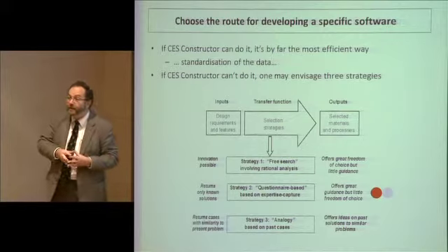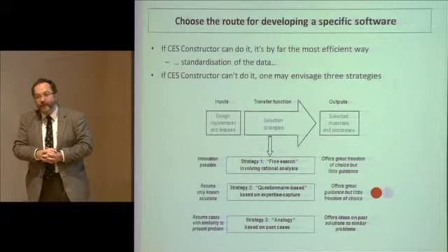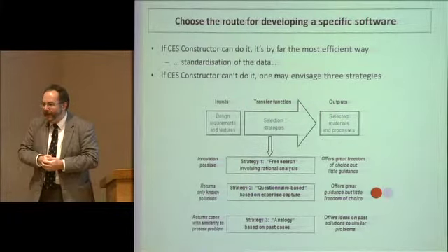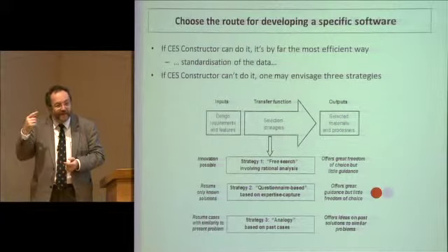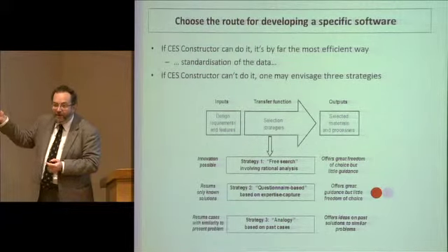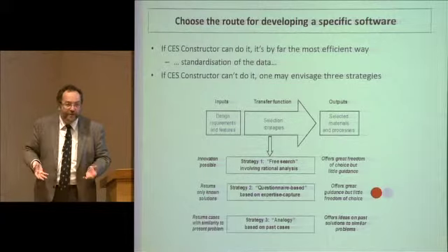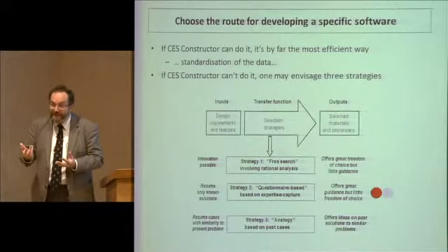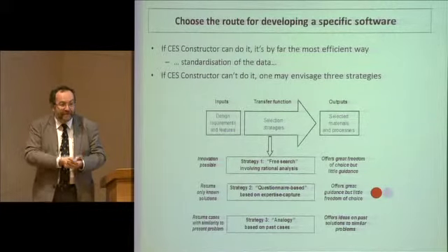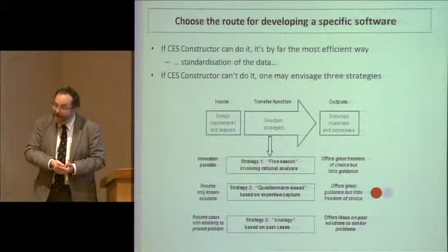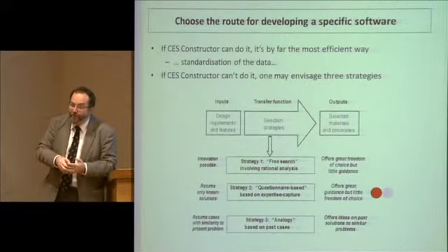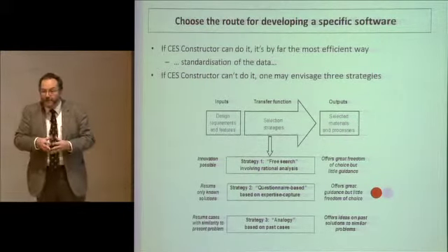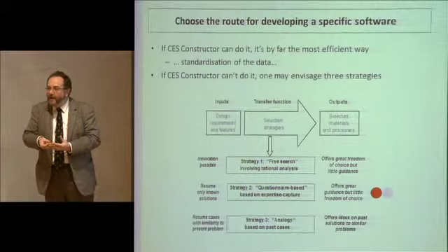But the ball itself, the question was, what should we make it of? IBM, pretty smart guys, but the first ball they made was made of lead. They thought, okay, printing, typeface, typesetting, lead, let's make these balls out of lead. But what you wanted was something that has, of course, a very low inertia, and that is not too soft. And obviously, lead was probably the worst solution possible. And if you find lead typewriter balls, they're really collector's items. So they really quickly moved on to other materials.